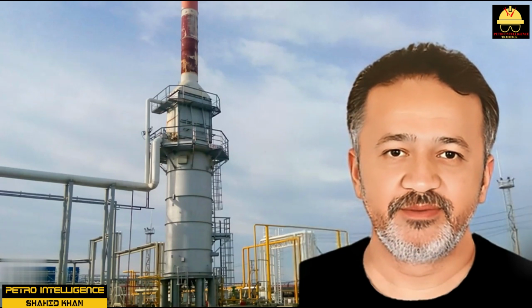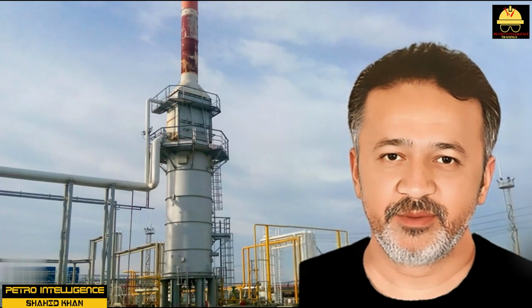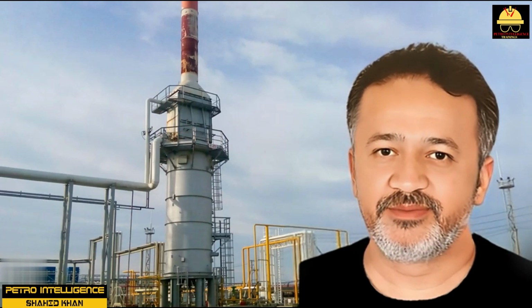Flame impingement. As flames reach up into the furnace, they occasionally touch a tube. Frequent or sustained contact is called flame impingement. This can weaken the metal tube and cause coking, which is the formation of carbon deposits in the tube. Flame impingement can sometimes be corrected by pinching back on the fuel supply to the affected burner.